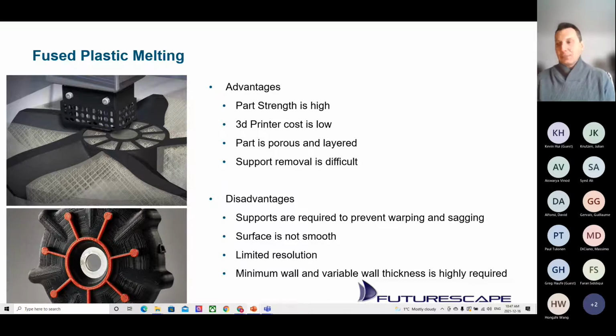The newer FDM machines now have soluble support, which means you can put it in a bath and the support material dissolves in a chemical bath. But again, if you have too much support there, you can get some of the supports entrapped in the corners and small features. So it's good to plan that support material sometimes with FDM. The orientation, and sometimes adding in your own supports, for example, to minimize the supports or add stiffness, can really help reduce that labor.